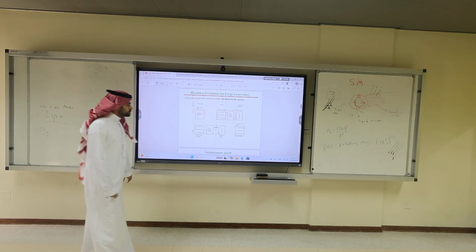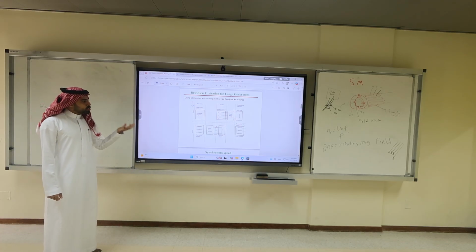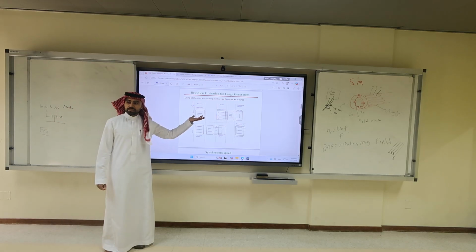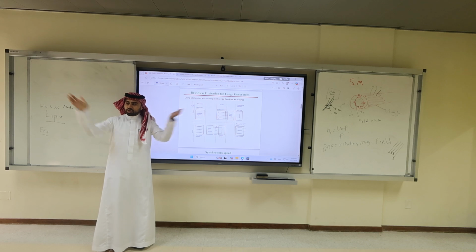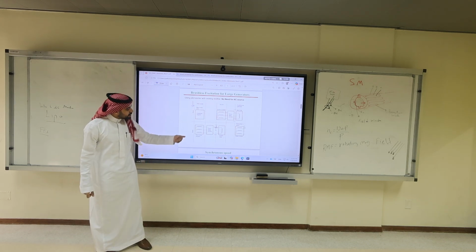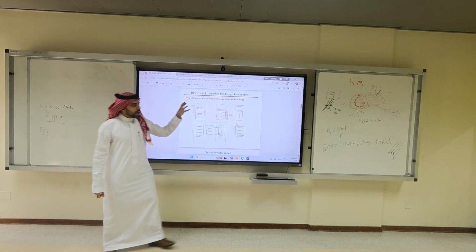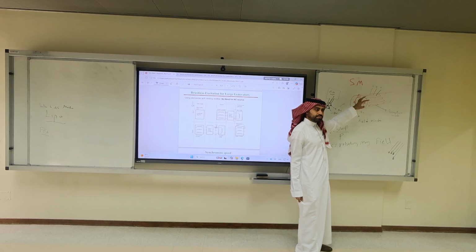So in the pilot exciter, we get now a permanent magnet, but does it have to be a big permanent magnet? No, it's a small permanent magnet. Why? Because I need to excite, I put it in the rotor, I start spinning the rotor.